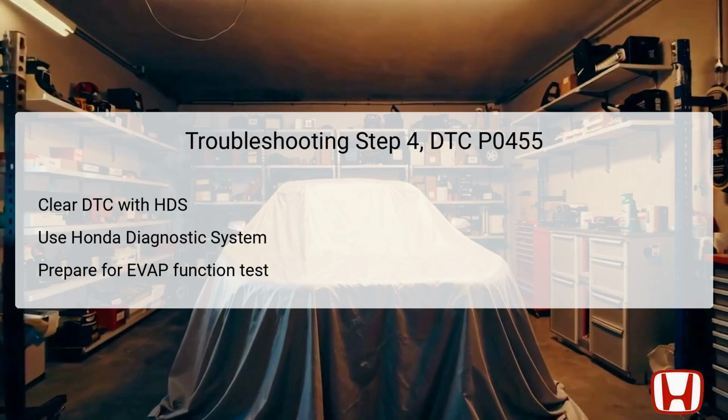In this step, use the Honda Diagnostic System, HDS, to clear the DTC. The HDS is an essential tool that allows technicians to interact with the vehicle's onboard computing systems and address any diagnostic trouble codes. Clearing the DTC helps to reset the system, allowing it to run fresh diagnostics on the components involved in the EVAP system.